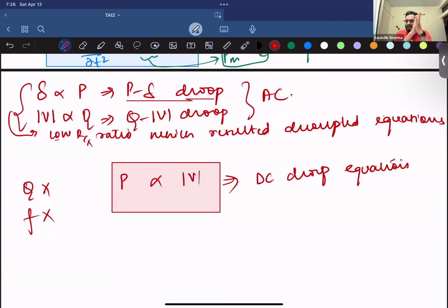Okay, let me think about it in this way. You have 4 kilowatt of load available at your end, right? And you want 4 kilowatt of generation to be able to have a voltage which is, let's call it 48 volt on the DC side. But let's say I'm supplying you with power which is 8 kilowatt. The drop would be less and the power available at your end would be high, right? But you won't be using that whole power. You would only be using 4 kilowatt out of that.